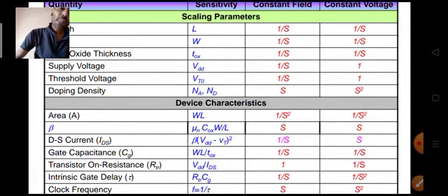Okay, then if you talk about the drain to source current, the basic equation for your drain to source current IDS is something like kn by 2 into twice of (VGS minus VT) into VDS minus VDS square by 2. So you see this equation, if you think about the linear and the saturation region, the equations are different. So I have told you that in the linear region, it is half of mu n Cox W by L (VGS minus VT) into VDS minus VDS square by 2, right?